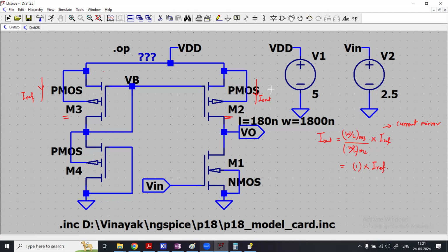But nowadays we are using short channel technology and BSIM4, which is an advanced model, up to level 49, level 44. We simply say BSIM4 is the latest and the most advanced available to date. That SPICE card will have hundreds of parameters, as we are going to see.